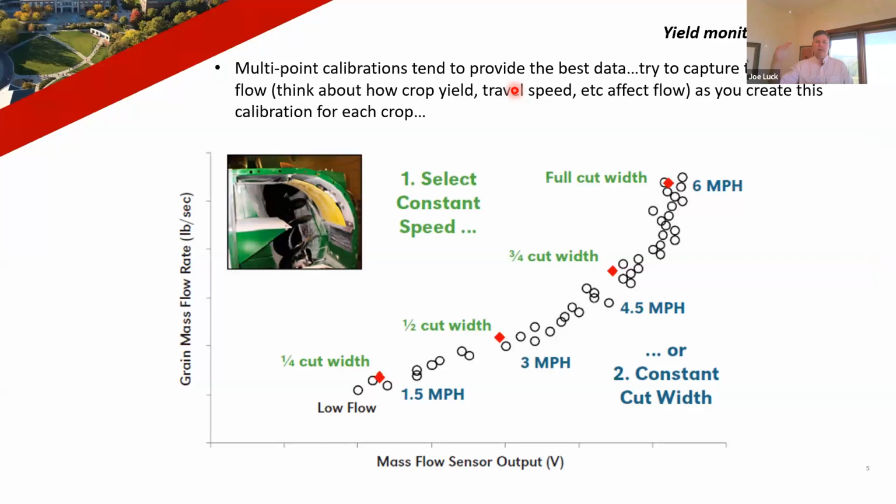So imagine you're averaging in, if I go 1,000 bushels, I'm doing multiple bin loads, the grain, while it's calibrating, the flow through that machine is going to continue to go up and down. And it's trying to average that in for that load. Whereas if we just have really short, very consistent flow while we're getting that calibration, it'll give you the best results. And this is kind of a way to visualize this.